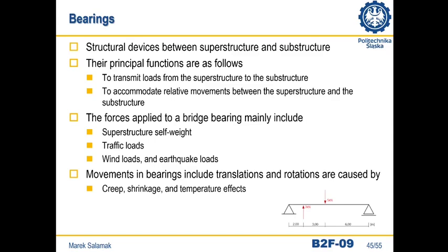Besides, they also allow relative displacements of the span relative to the support. Reactions are mainly due to self-weight, vehicle load, and wind or ground excitations. A movement can be caused by temperature changes and shrinkage and creep of concrete.